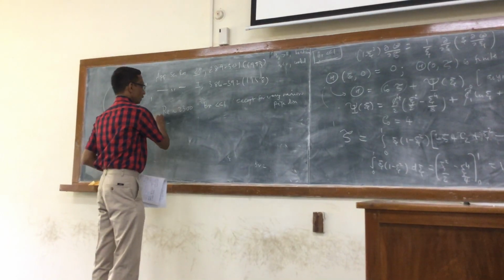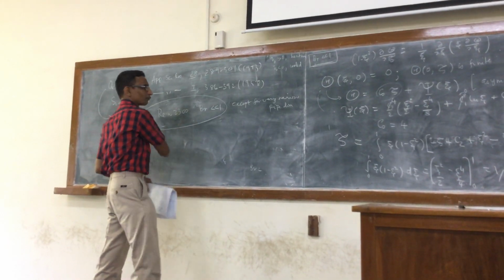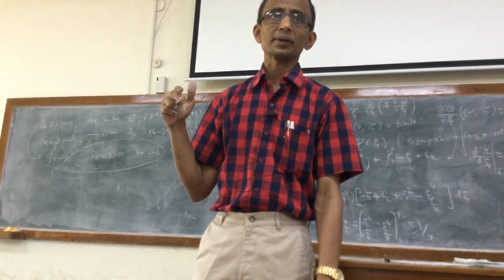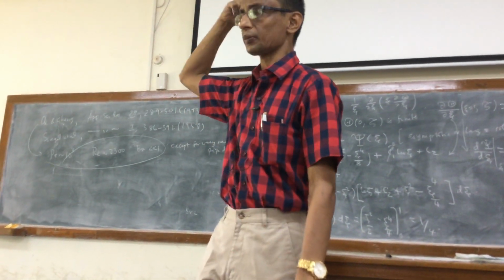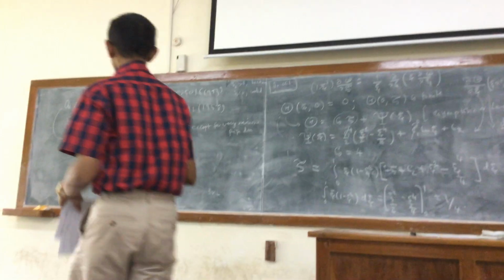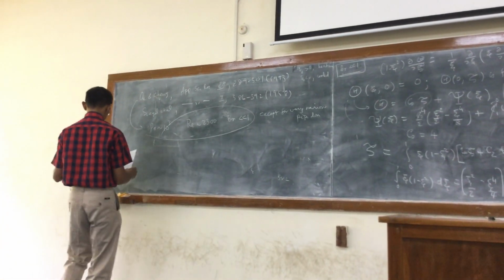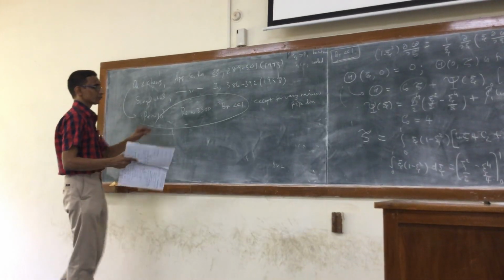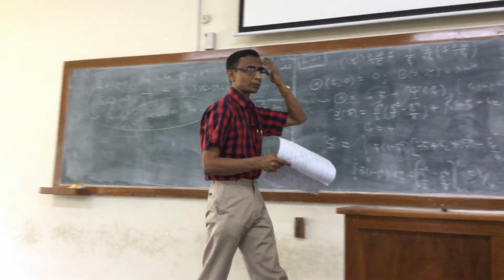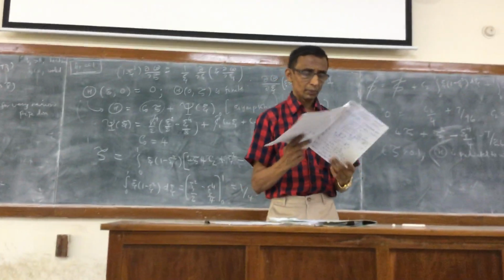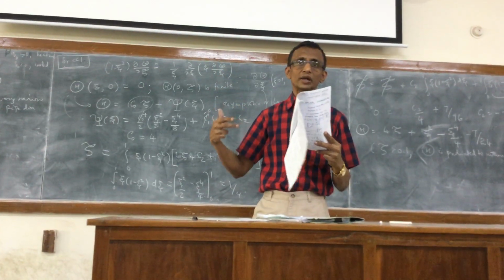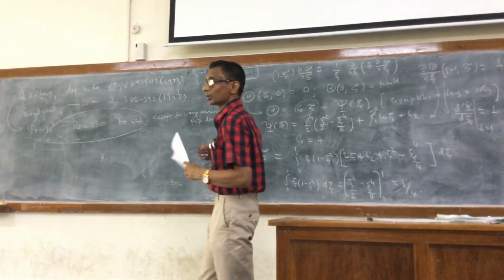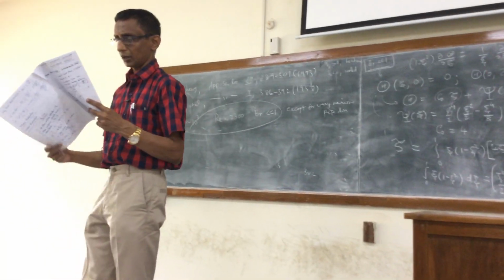So this is a good typical set of conditions they have given. In the table they have given a whole host of practical conditions. You see, Prandtl number 1000 corresponds to a liquid that's quite high, but it corresponds to normal liquids. And so for laminar flow, they say that the Brinkman number is much less. So they've given a whole host of conditions for which the solution where the viscous effects are neglected will be